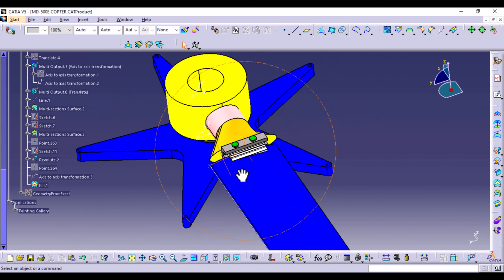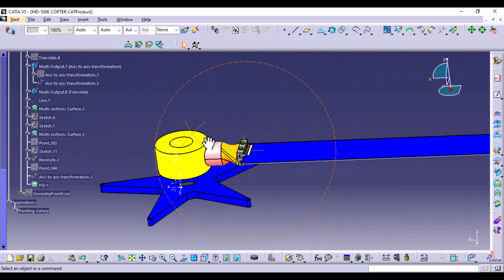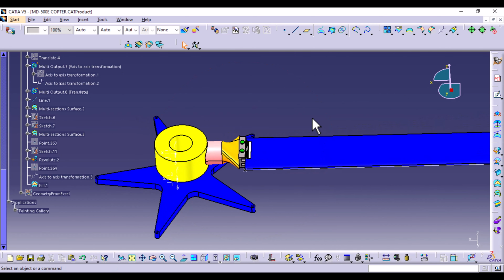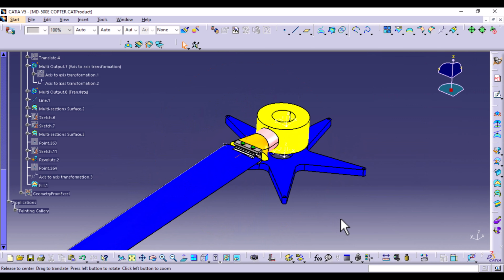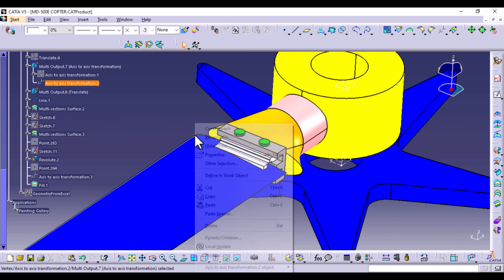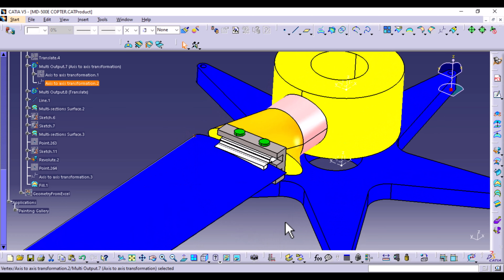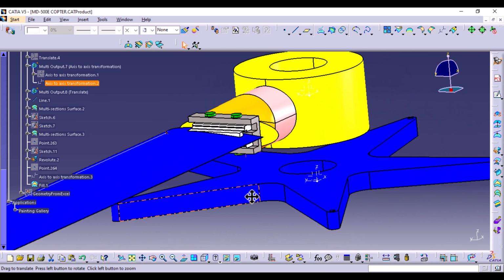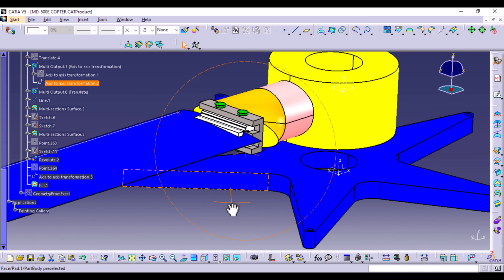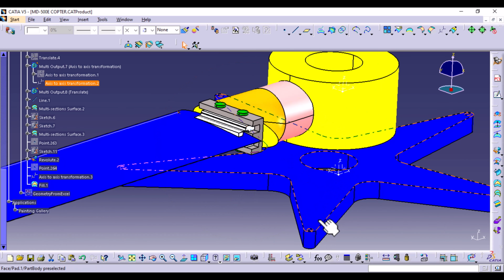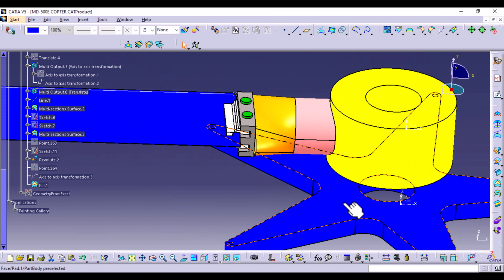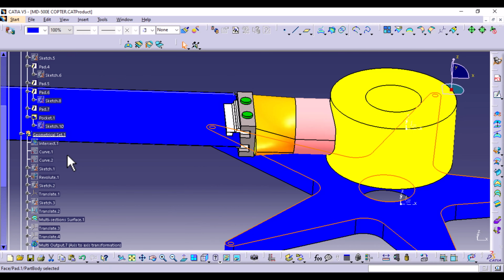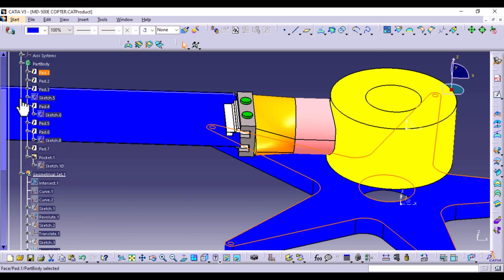So we've got one blade. Remember, we are only creating one blade section, and then we are just going to create a circular pattern. So you don't have to worry about creating more blades. Once we are done with one, that's it. Now there is an extruded surface here that connects with this star. So this star is definitely too large. So we're gonna go back to where we were creating this. That was pad 1.